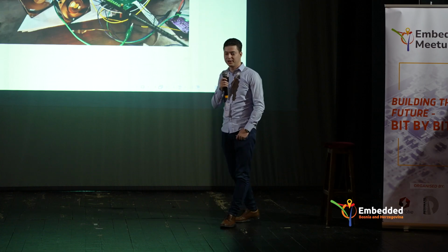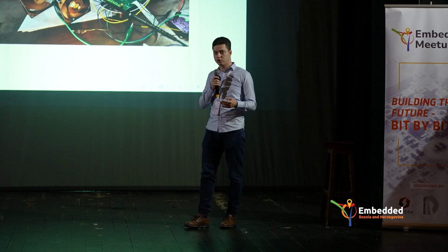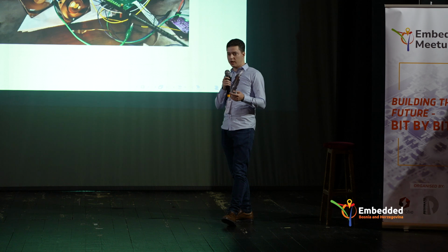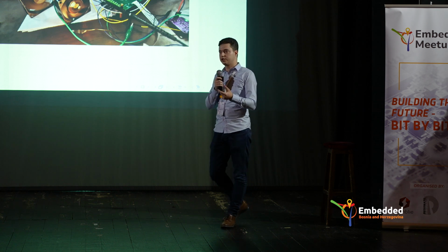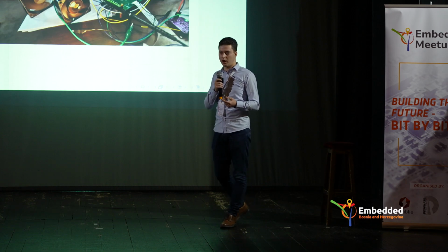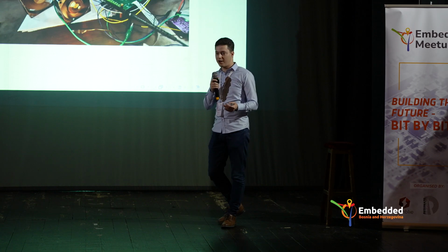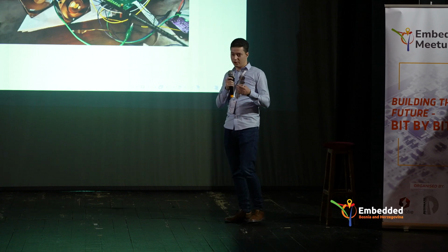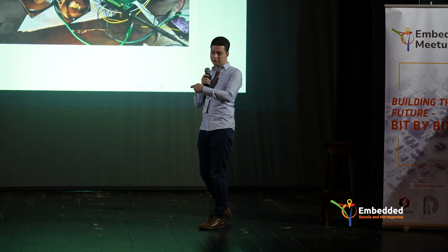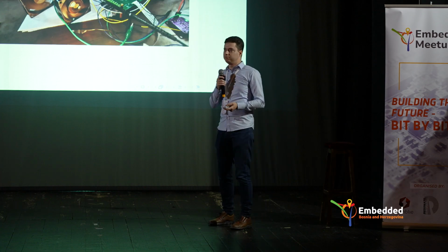To be quite frank, it was a bit complex, but each step of the way, from the camera capture itself, to ensure that the image capture is well timed and not prolonged. So essentially validating the pixel clock itself and the speed of the image capture. Then afterwards, we need to validate the hardware synchronization. Essentially, it boils down to using an oscilloscope quite often. And then at the end, we will see the end result on the Python app, which is the only truly valid validation, let's say.